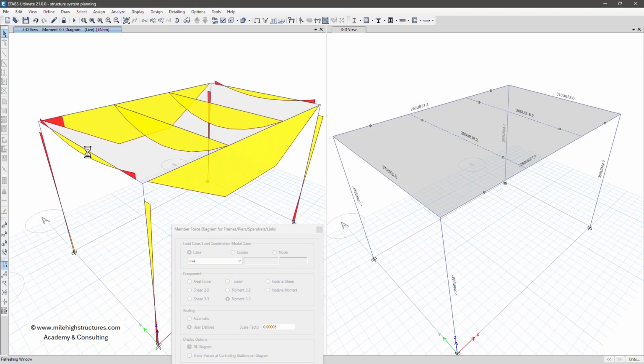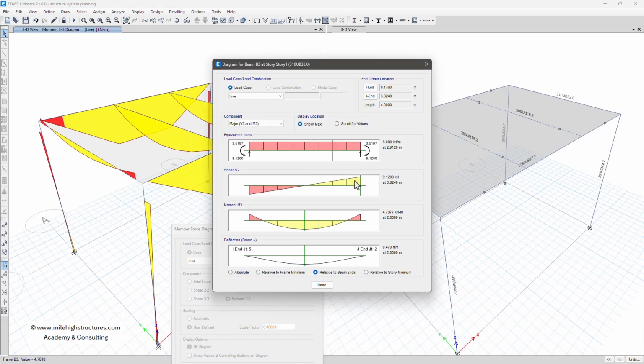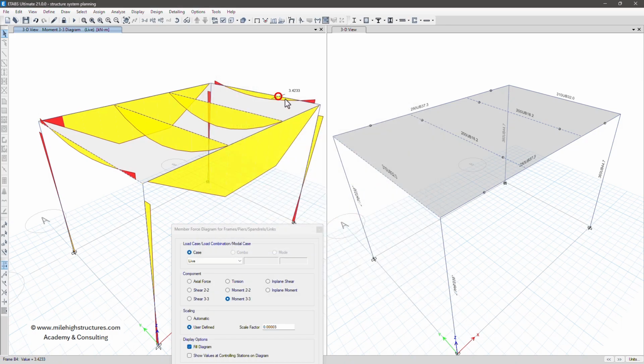Now, this is basically a moment frame here. So we can just left click here and then again right click here. So this is the bending moment diagram for a fixed beam. As we had made this a moment frame, for this beam here the bending moment is approximately 4.8 kN·m. Same is the case here also.